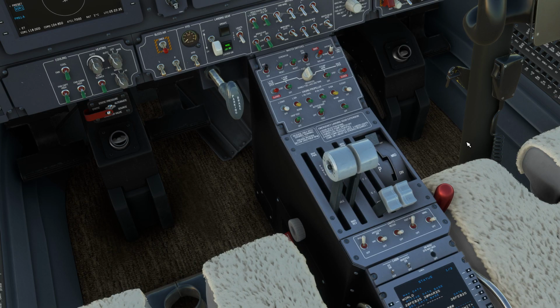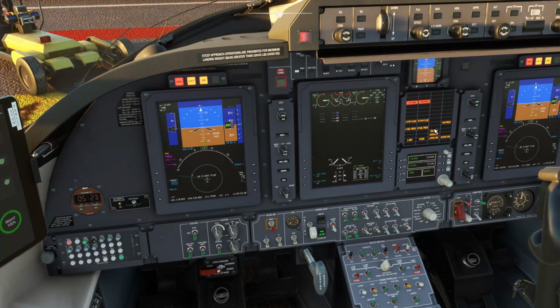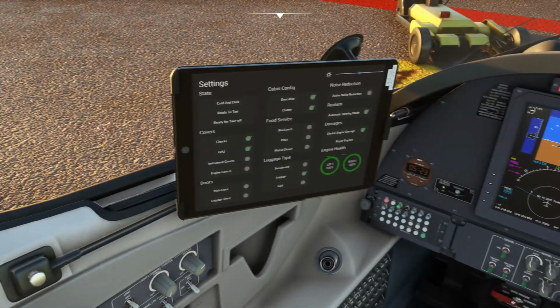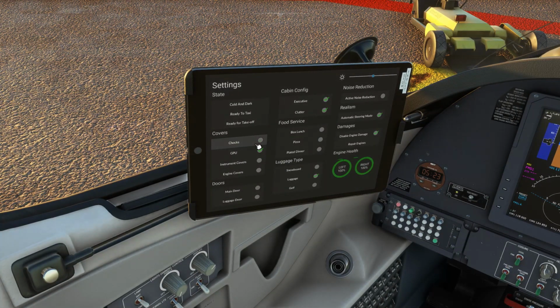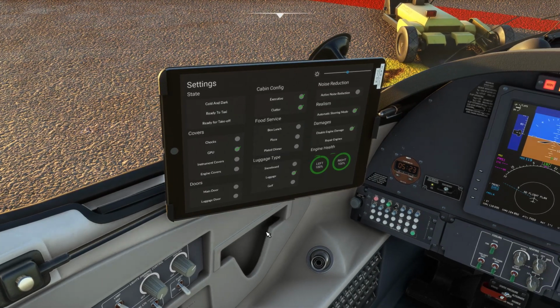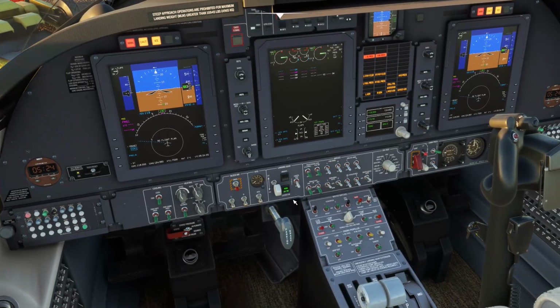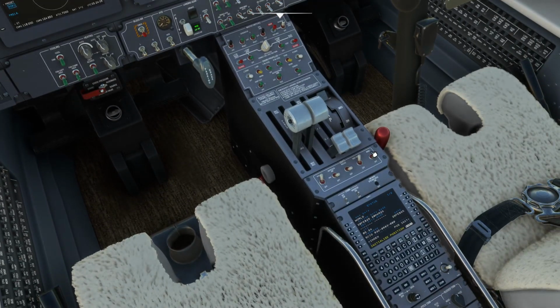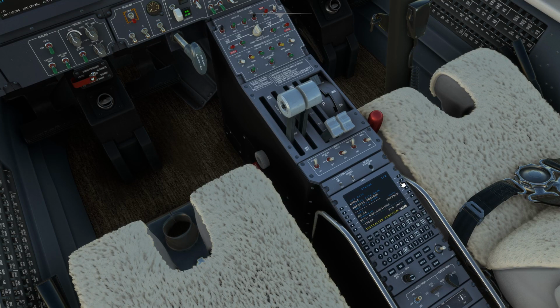Crew pax briefing. Let us get some ATIS going, because it would be nice to know what kind of weather we have. But in the meantime, parking brake is set. Chocks we shall remove. We still have GPU for now. Engine and pitot covers we have taken off. And then, because we do have external power, we'll go to programming FMC.